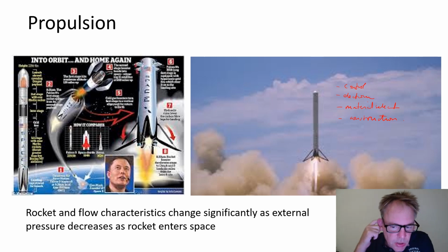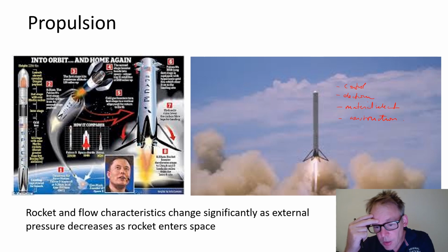There are some interesting design features associated with the pumps. There's a turbo pump, a gas turbine engine driving a turbo pump for both the fuel and the oxidizer. The fuel in this case will be methane. This leads to a very high mass flux and an enormous thrust.